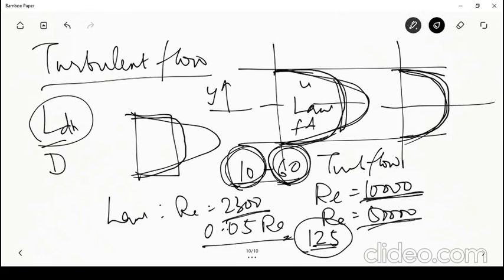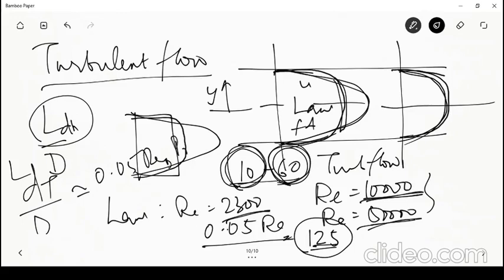So if I have a 300 meter pipe, the developing length of the pipe, L_DH, is much smaller as compared to the actual length, and therefore you don't really need to worry about the extra pressure drop that happens in the first half meter, and you can calculate the total pressure drop in the entire pipe, assuming the flow to be fully developed in the entire pipe. In the same fashion for heat transfer, if the flow is very highly turbulent, then you don't really have to consider the entry length unless the pipe is extremely short. Okay, so that is the thing that we will be looking at.